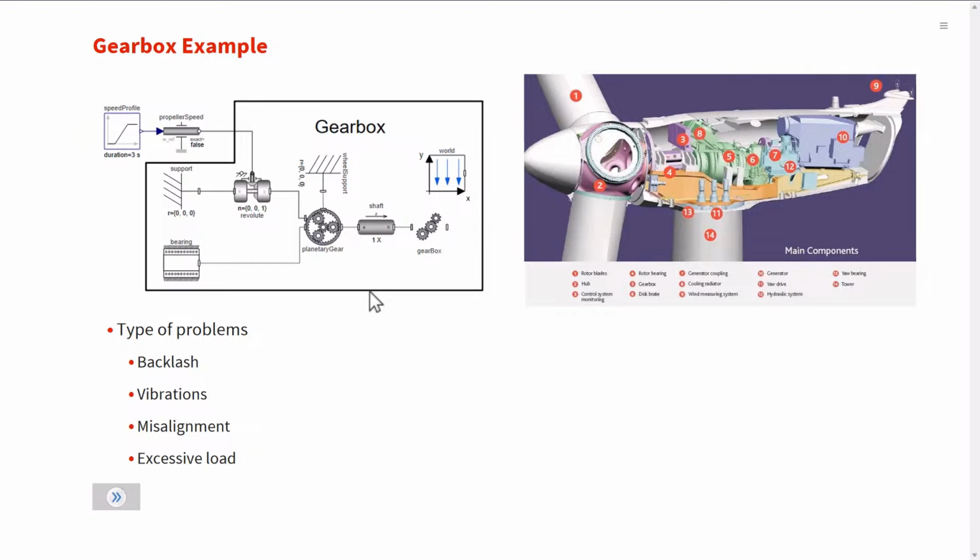We will now examine the Acciona AW100/3000 gearbox, a key player in wind turbine operation. Identified here is item number 5. It is a complex assembly featuring a planetary gear and a 3-stage gearbox. So this is the gearbox we are looking at inside this Acciona, and this is how we model that gearbox using rotating machinery: a planetary gear, a 3-stage gearbox, and one shaft in between.